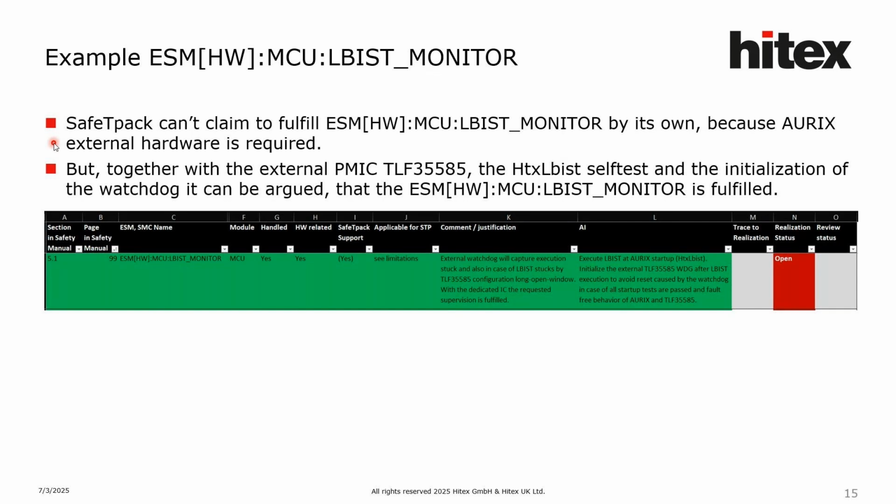But in the combination with the external watchdog, with the LBIST, with the Hitex LBIST self-test and the initialization of the watchdog, it can be argued that the LBIST monitor is fulfilled.